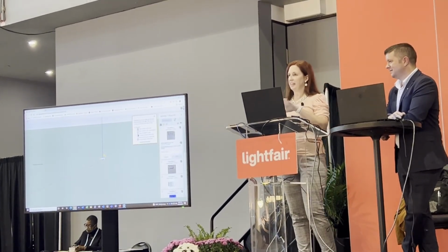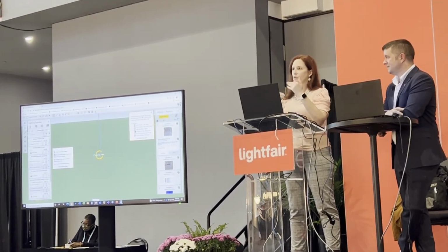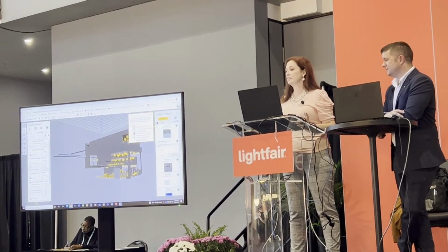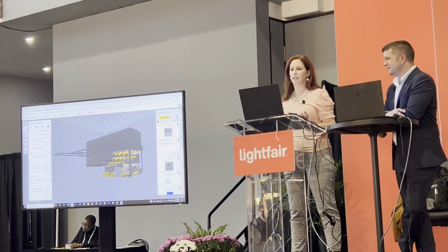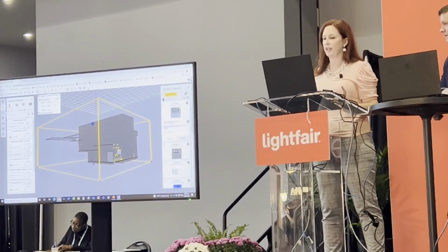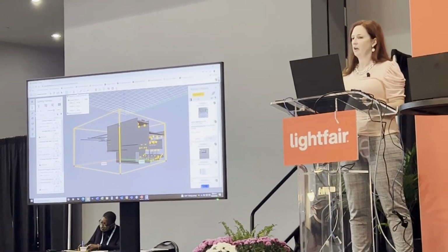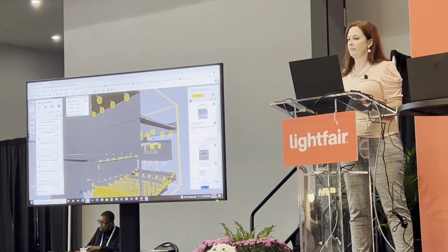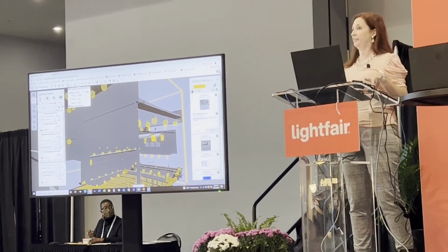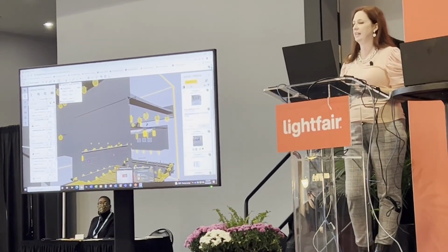what I just demonstrated was if all of the fixtures had the wrong position or the wrong orientation. But most often when you're using the aimable fixtures, you're not going to have everything aimed in the same direction. Whereas in Revit, the way we have our family set up, you can adjust the tilt angle, but then all of the fixtures have the same tilt angle.